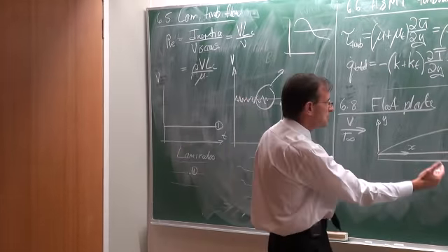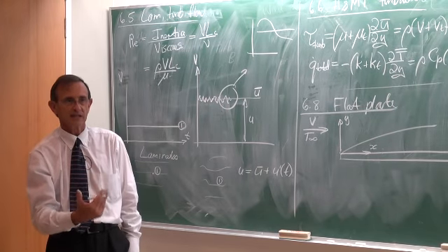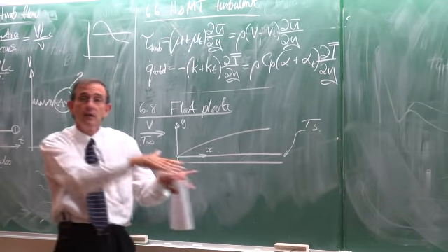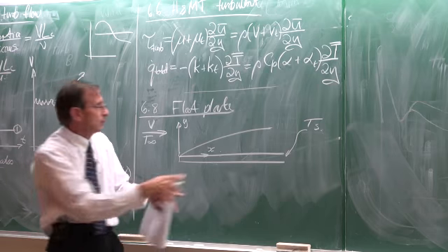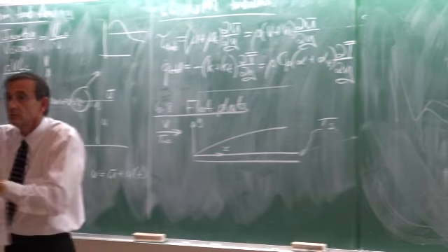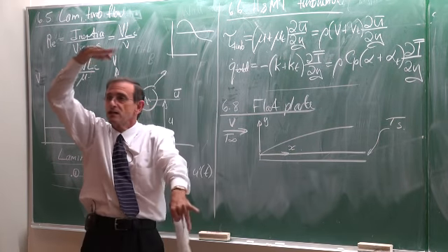And then they wanted to look at the velocity distribution and the temperature distribution over a flat plate, the heat transfer over it. Now this case is more complicated than Couette flow, because we also have a velocity in the y direction, because this is just a boundary layer developing over a very thick flow.